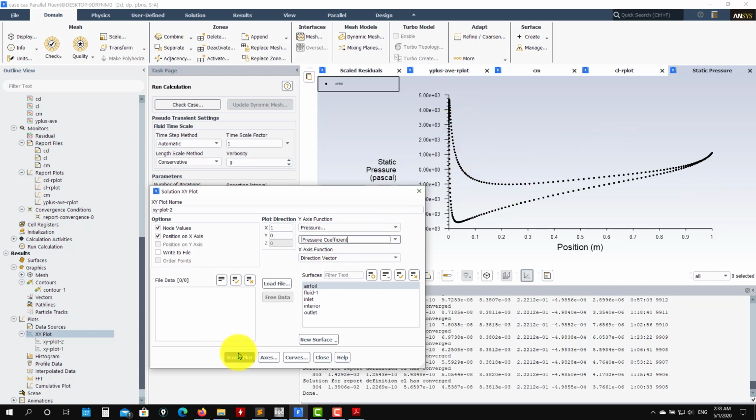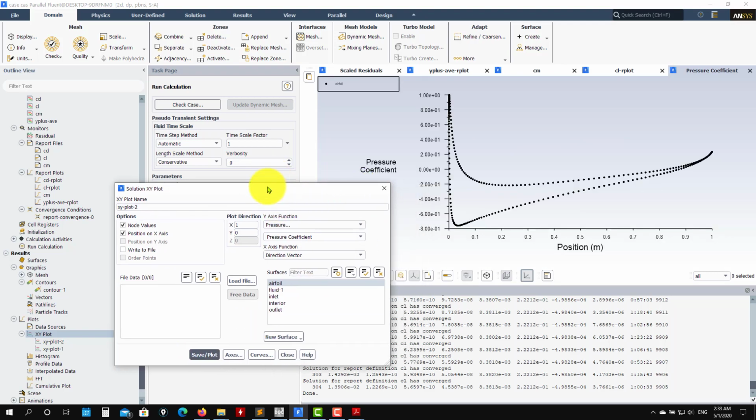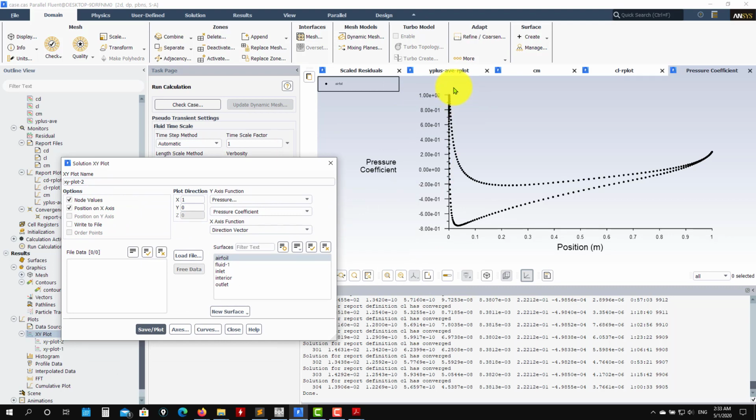Also you have CP here that has been normalized using the previous coefficients. See that we have it here, 1 at the peak, the stagnation point, your distribution. To have it like the aerodynamic plots, you need to invert the axis. Usually this is multiplied by -1 and you invert it. Okay, it doesn't matter. So this will be the suction side and the pressure side, the intrados and extrados.